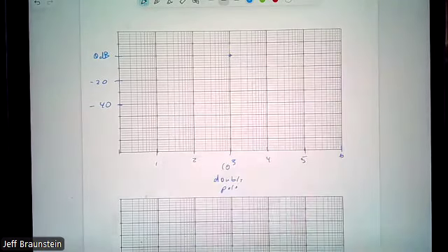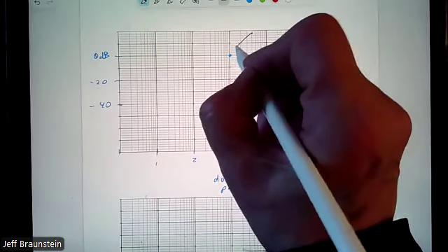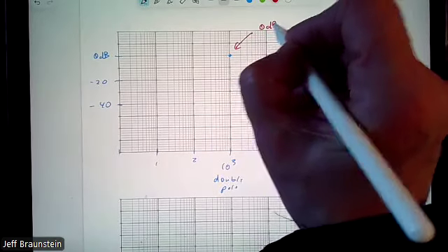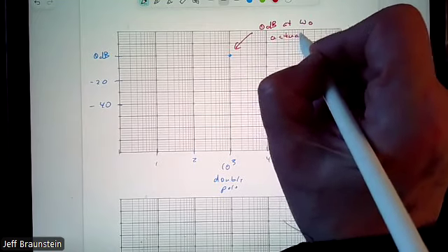And we've proved this before, it's been a while, I don't expect you to remember. But at the resonant frequency itself, our dB value is 0 dB. That's an actual value. So for this circuit, 0 dB at omega naught, actual value.